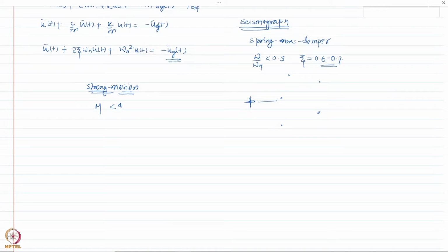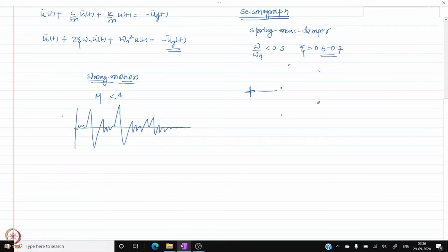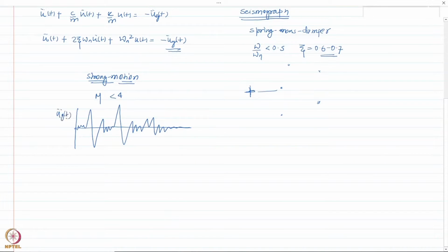So these accelerographs are actually triggered when the acceleration is above a certain threshold, or when they are calibrated to be triggered with some other mechanism. So what do we do? These accelerographs would give you strong motion, and they would also report the strong motion duration of an earthquake ground shaking. Again, it is based on the same principle that you are only bothered about the ground motions which are going to have any realistic effect on the structure.